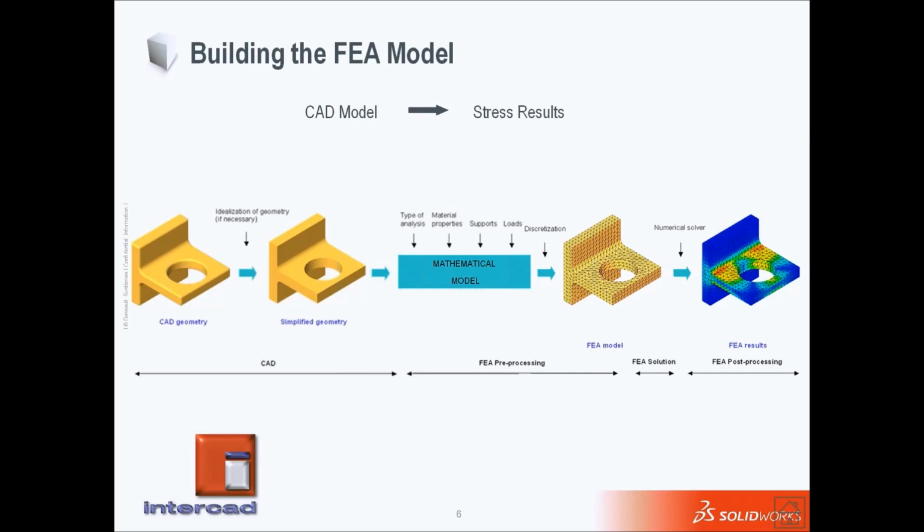After this would be the connection of our actual model to the real world. This is defined by a series of supports we put on the boundary of our model. And next is the physical condition, which is loads, pressures, and everything else imposing displacement, deformation, or any motion.